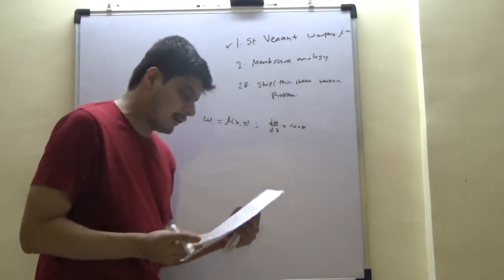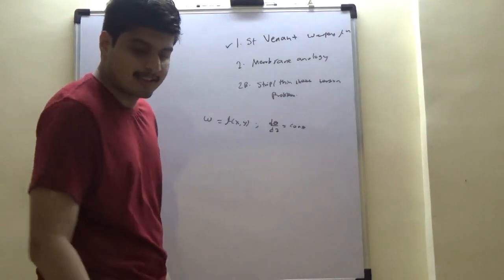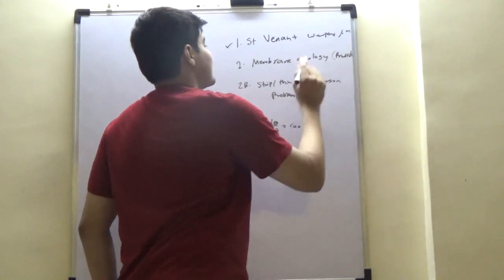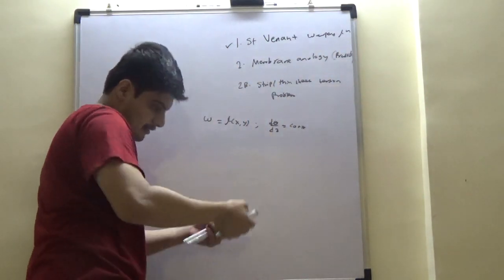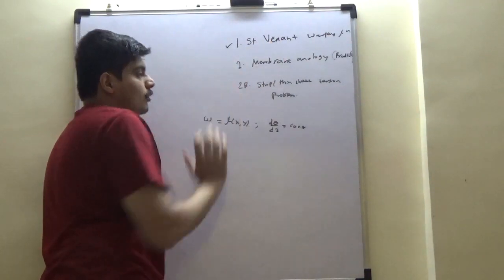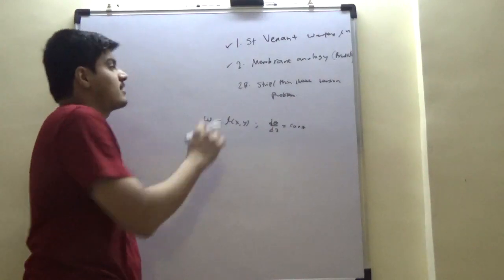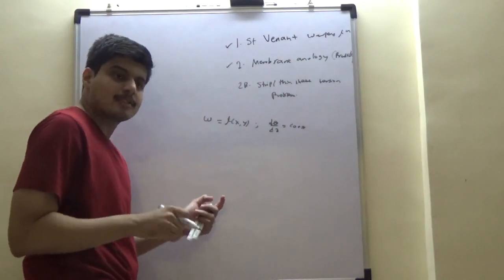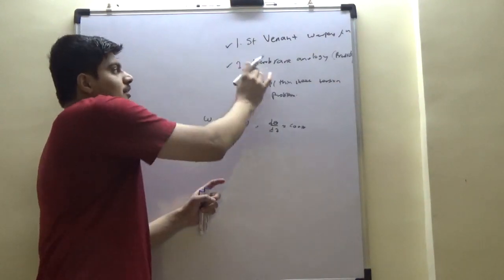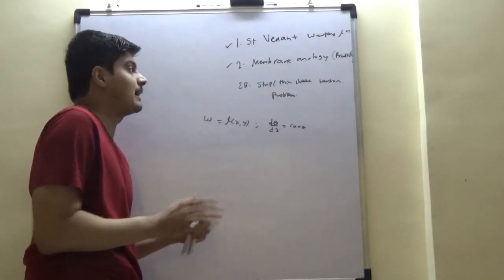Again, this was done by Prandtl, and let us reconfirm that because this is a GATE examination question, right? So Prandtl and his colleague. So it is called Prandtl's, but it is Prandtl and his colleague, right? So it is his analogy that if you look at a membrane which is squeezed and which warps out, twists to resist that load, the problem of torsion and membrane are mathematically or physics-wise equivalent. The phenomena governing is slightly different, but the formation of the problem, the setup of the problem is such that the analogies are identical, and it simplifies your task to solve these equations much in detail.